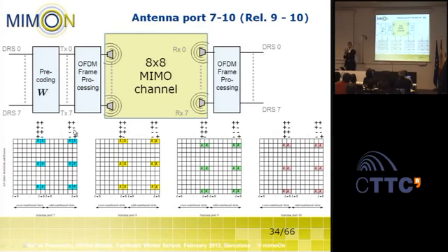These are orthogonal sequences used by different antennas. So in this case, the antennas are not separated only due to the orthogonal time frequency resources used for the pilots, but also the symbols modulated on these resources are chosen as orthogonal. In this scheme, we can distinguish up to 8 different reference signals, so at the user equipment we can estimate all 8 channels to the 8 transmit antennas. So we can measure the entire 8x8 MIMO channel in this case.